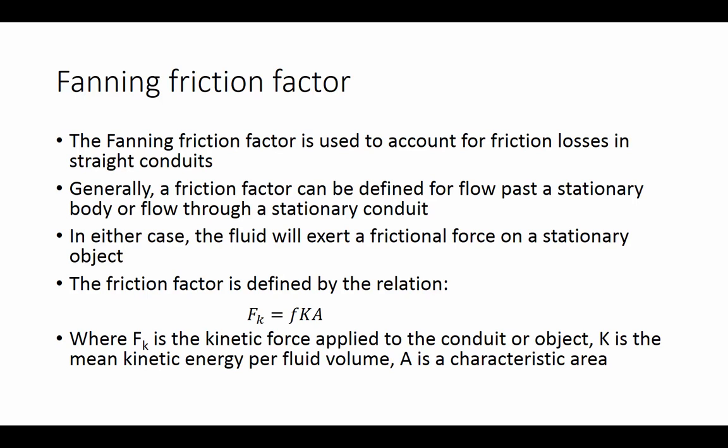One thing we can do is use the Fanning friction factor, which is used to account for friction losses in straight conduits. And generally a friction factor can be defined for flow past a stationary body or flow through a stationary conduit, which in this case is what we are considering here. But in either case, the fluid will exert a frictional force on a stationary object. And the friction factor can be defined by this relation right here.